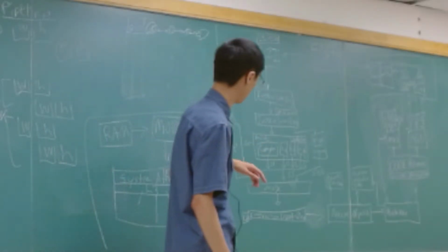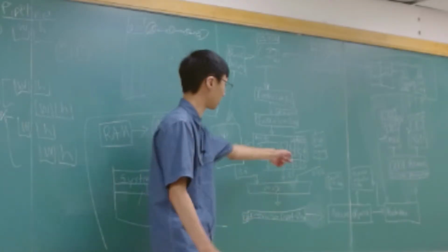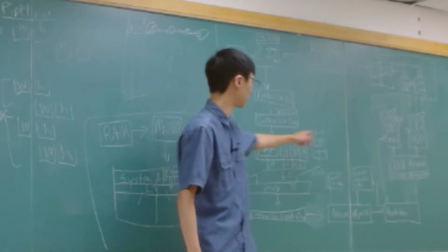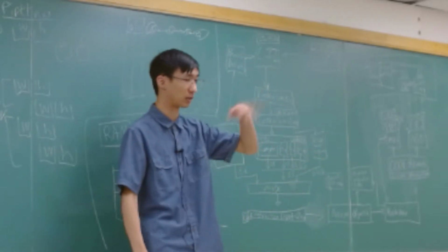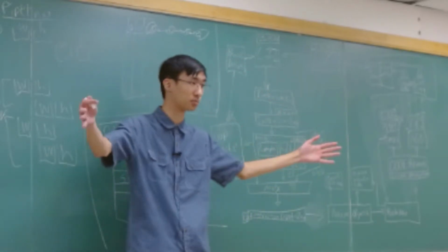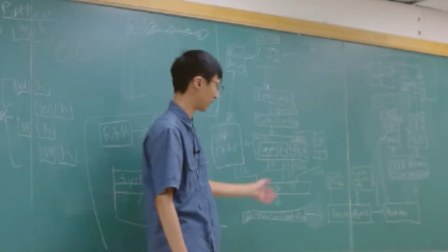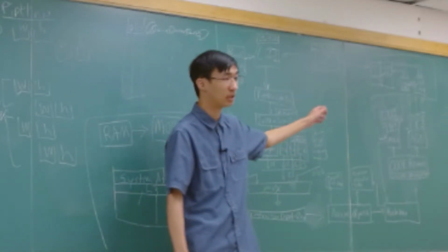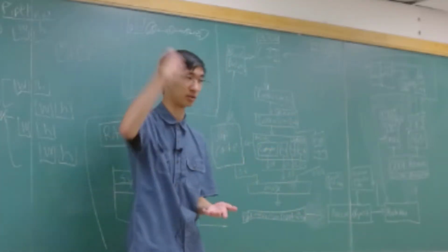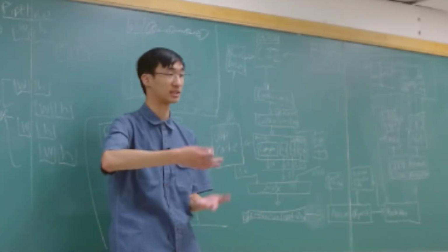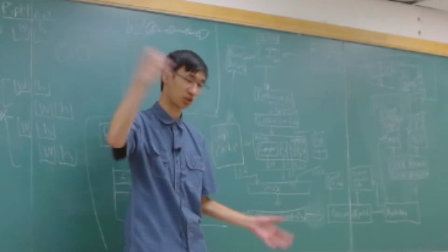Other things you might want to note: try not to use that complex decoder if possible, because it stalls the other simple decoders. Try not to use anything that hits the microcode sequencer. That thing takes four micro operations per cycle, which means you can stall multiple cycles trying to output a more complex instruction. For example, on ARM, I remember that the microcode sequencer started dumping a ton of micro operations because it didn't know how to do a divide, because divide didn't exist. So it just started dumping micro operations.